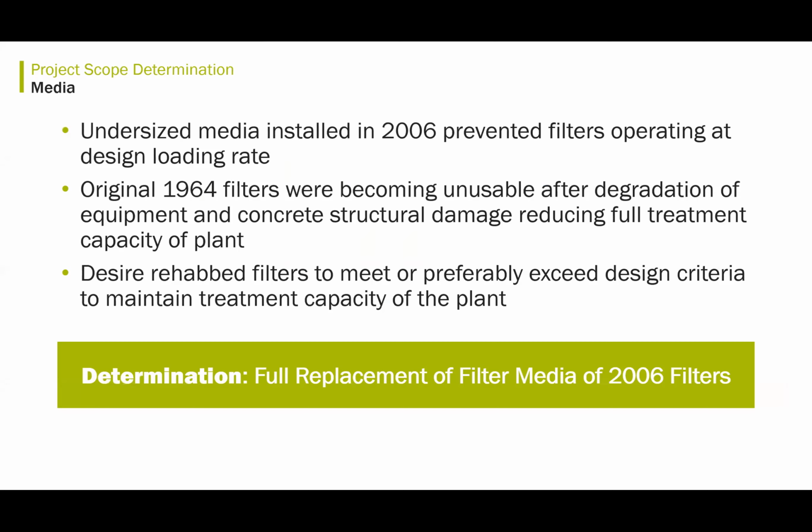So as I indicated, the media that was installed in 2006 was undersized, and that prevented the filters from operating at the design loading rate. And the original 1964 plant filters have become unusable after degradation of equipment and concrete structural damage. And so they're looking at rehabbing the 2006 plant to see if they could meet or exceed the original design criteria.